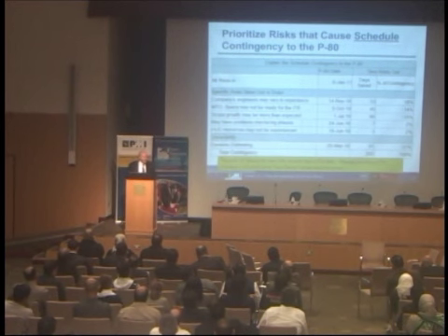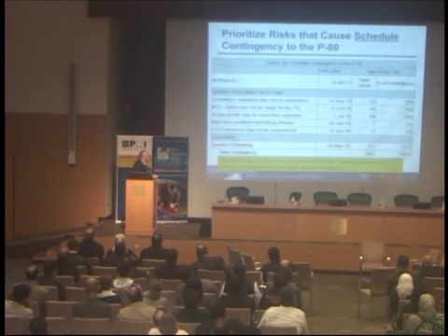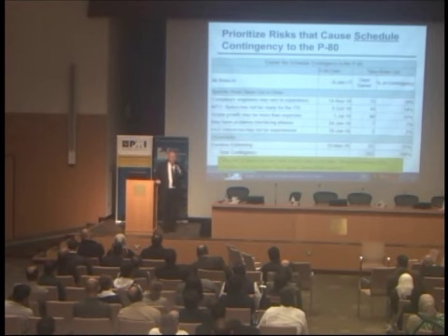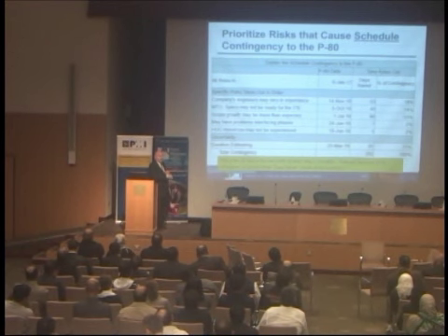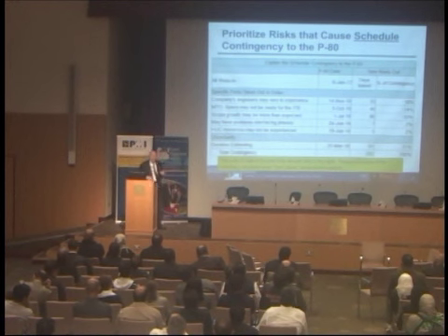but then you get to this one, and you've got a fair amount of schedule risk to fix. And you go down, and finally, the inherent variability in duration estimating is down here. It's 91 days, but it's inherent. You're not going to mitigate that. You've got to live with that. So all of a sudden you realize, I can't get back to my 2nd of March 2016 because the last 91 days, and these are calendar days, this is an Excel spreadsheet, calendar math, are in the inherent category. I've got estimating error there, but there's also inherent.